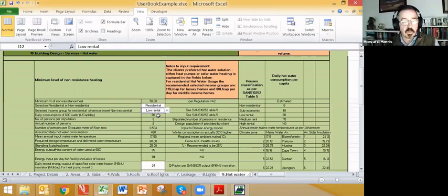Now bear in mind that not all water is used at 60 degrees, and much of it is mixed to a lower temperature, but effectively one needs to provide for enough hot water at approximately 60 degrees exiting that geyser during the course of a day. So that is our consumption, or our usage, and it totals 480 liters in a day.